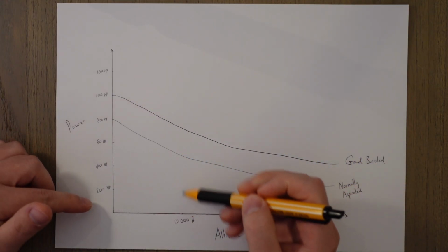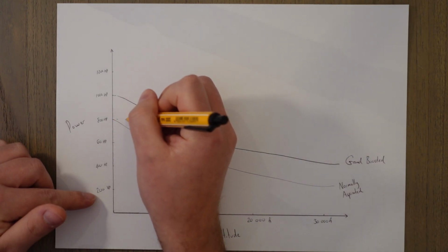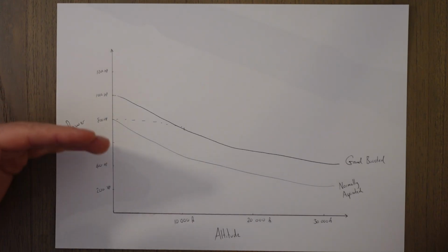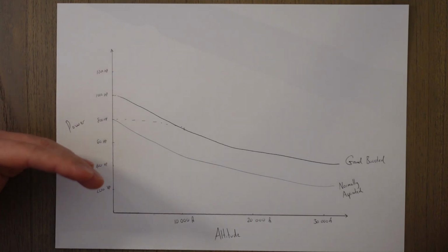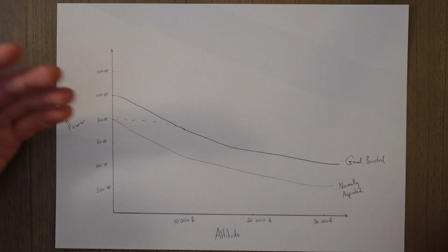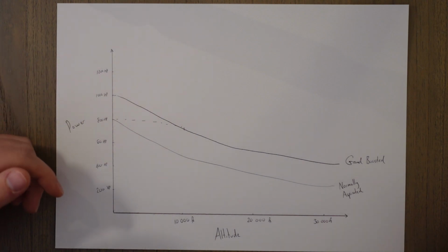You can see at 10,000 feet, we've still got roughly the normal power that we would have in a normally aspirated engine, just by boosting that ground level with the same drop-off. It's just adding more, same drop-off, you're going to get more when you're high up at altitude.